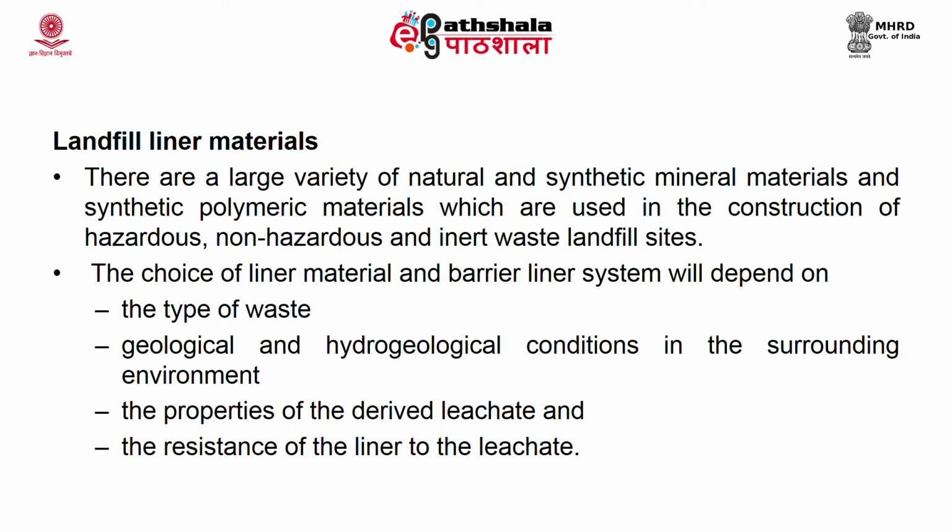The second criteria which you have to look into is the geological and hydrogeological conditions in the surrounding environment. This I have already explained. You have to look into the geology, what is the nature of the soil, what is its porosity, what is its bulk density, then the water table level, and the percolation rate or infiltration rate. All these things you have to consider before you choose a liner material.